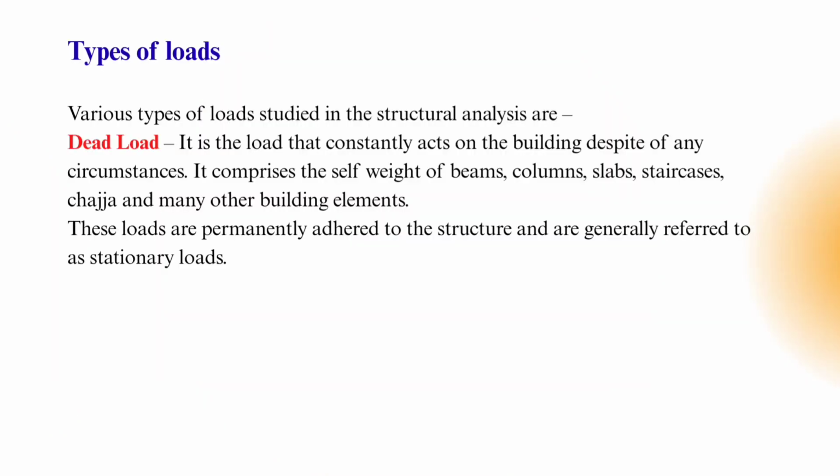It is the load that constantly acts on the building despite any circumstances, and it is nothing but the self-weight of beams, columns, slabs, staircase, and the many other building elements. And these loads are permanently added to the structure and generally referred to as a stationary load.